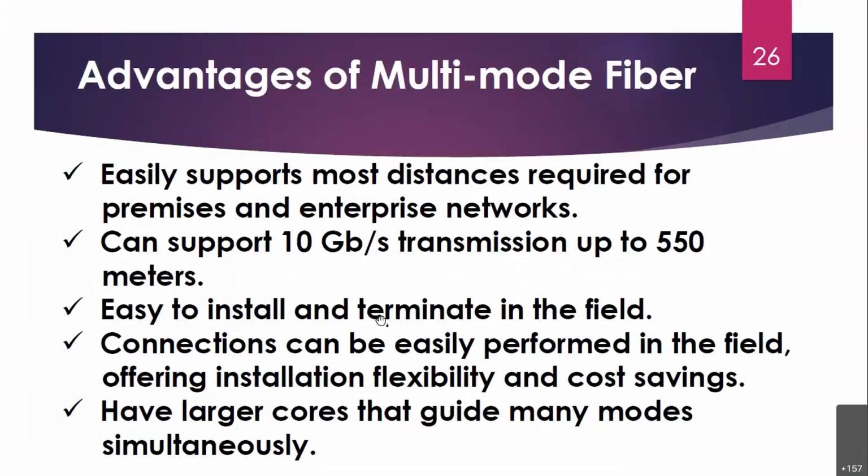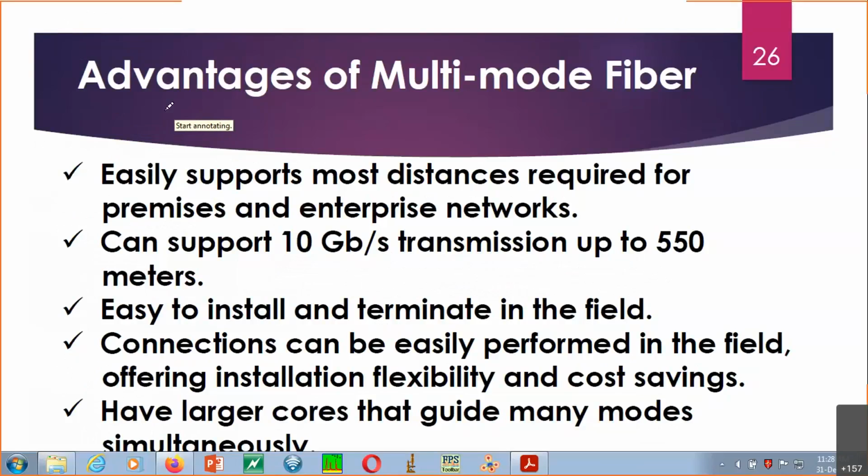Okay, so come to this. Let me annotate again. Now we'll discuss the advantages, as we have discussed in the case of single mode optical fiber also. So you see the advantages of multi-mode optical fiber. First, it can easily support most of the distances required for local premises or enterprise networks. So one can go for this. That is preferable. As I said, in the local distances, always you have to go for the multi-mode.